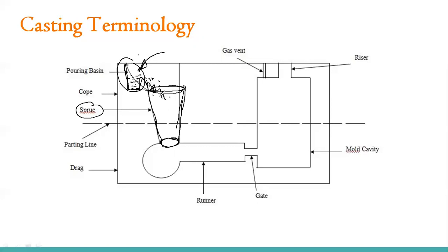Why are we using a taper section? Because the molten material coming through this pouring basin does not completely cover this area. A little bit of area is still left. So if we use a completely cylindrical portion, a hollow cylinder, then whatever area is left in the beginning, this size, will be left throughout this length of the sprue.